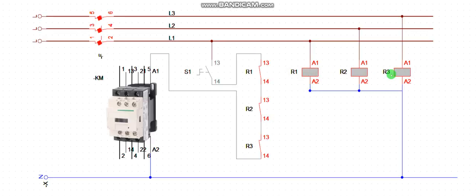Look at all the relays being energized, and their contacts have closed. So if I close this contact, my signal will flow completely. The circuit is going to complete to my contactor. So let's energize. Look, contactor closed. If I de-energize, contactor disengages. If I energize, contactor closes.